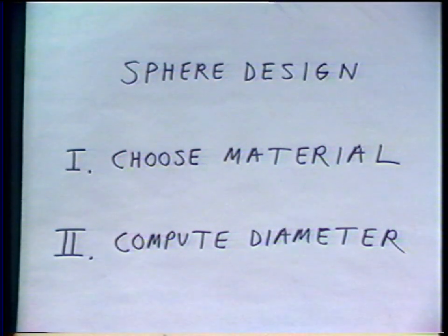Considerations in the choice of the material include hardness, machinability, corrosion resistance to seawater, uniformity or lack of texture, knowledge of its elasticity, availability, and cheapness. For all of these requirements, copper in its electrical grade form is outstanding. This conclusion has been completely confirmed by the experience of the Institute.